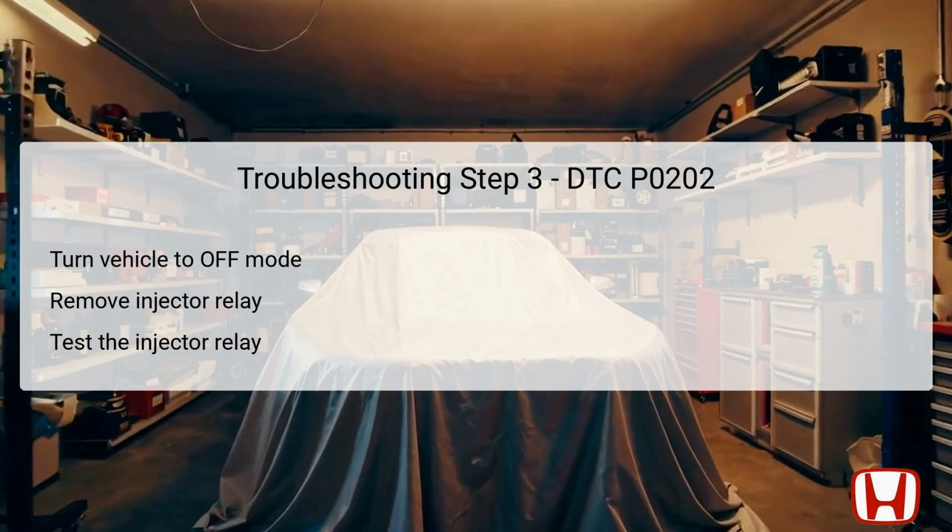This is done using specialized equipment or a multimeter to verify the relay's continuity and functionality. If the injector relay tests faulty, it will need to be replaced to restore the proper flow of electricity to the number 2 injector. If the relay is confirmed to be operational, then you will proceed to the next diagnostic step to further explore potential issues.